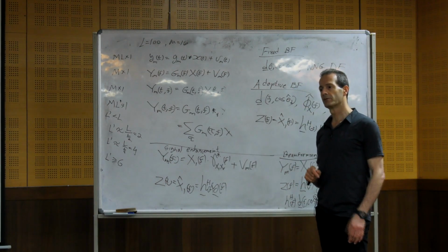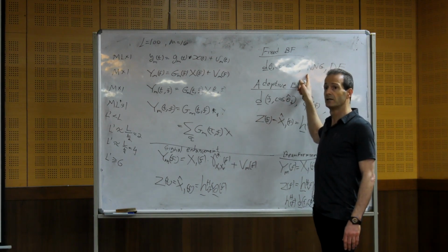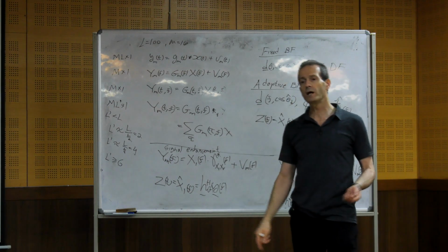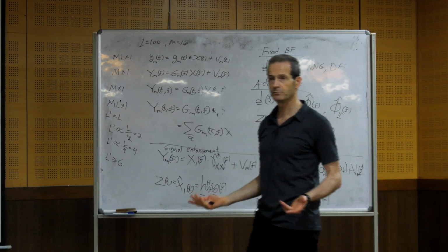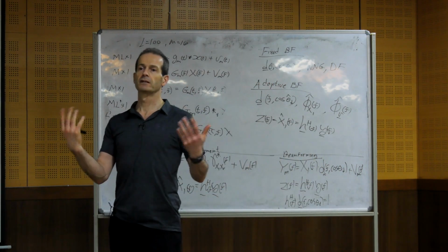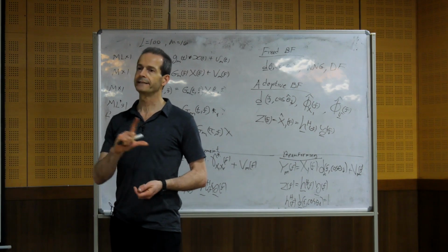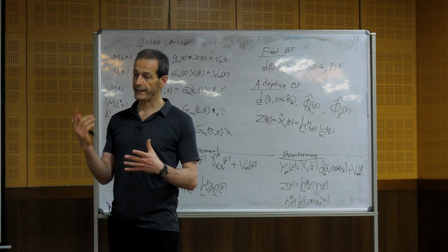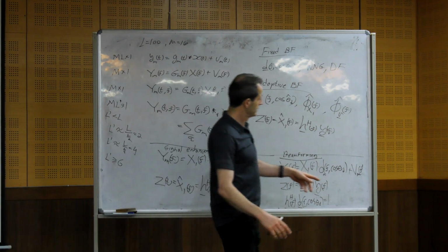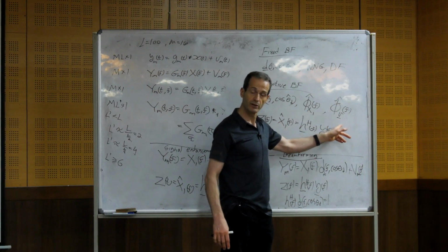But then, for a fixed beamformer, I need to assume a certain noise field. Maybe white, maybe diffuse, maybe a combination. I don't know the spatial field of the noise. So do I want to add another algorithm to estimate the variance of the correlation matrix of the noise?